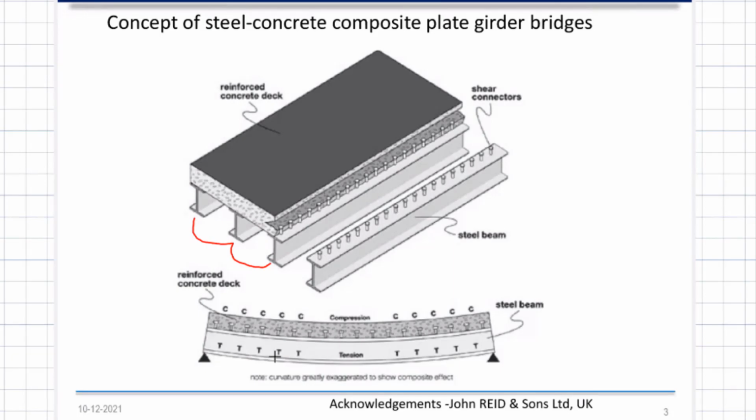Rolled sections are rarely used, right? You can use rolled sections, but there is a bit of difficulty in getting the sections right. Many of you may know that you can get up to 600 depth of steel beams, but then made to order, Jindal can make about 900 maximum in India. So usually these plate girders are three-plated systems, in which I have a web plate and flange plates connected together. That is the basic load workhorse.